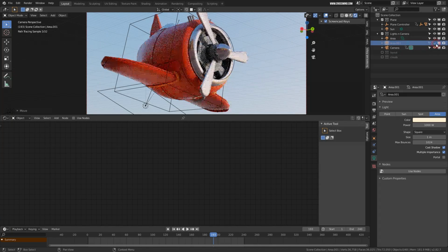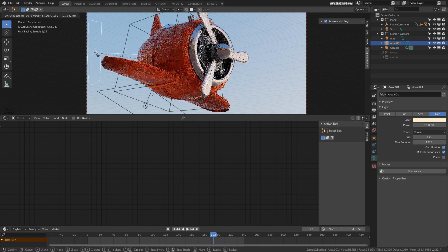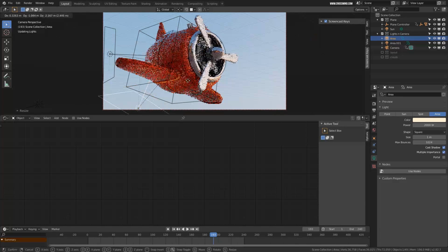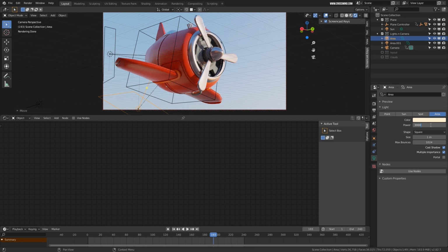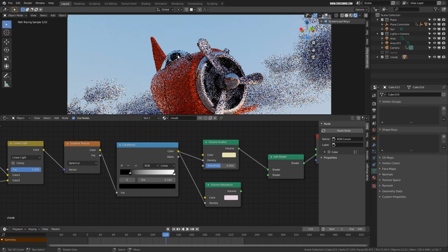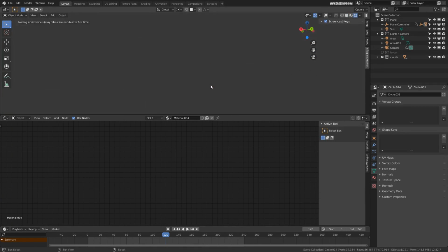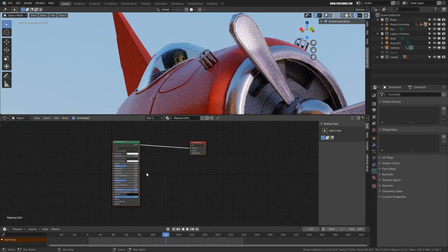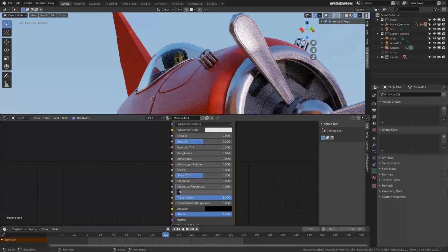Okay, maybe make it 2000 and see. Alright, so we have some bounce light over here, and also if you see over here, we need to adjust this material. If you go to object and index of refraction for this glass part, make it 1.3.